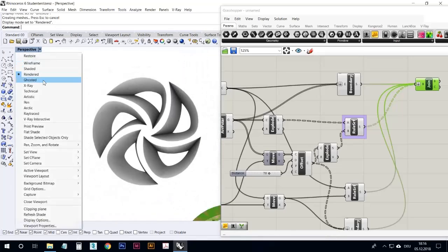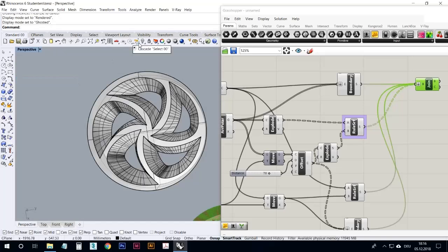And to be absolutely sure, we can go to this select function here in Rhino and click the little arrow. Then a lot of selection tools come out. For example, this one is very handy to use if you're going to 3D print this. We click the little arrow and ask Rhino to select all closed polysurfaces.